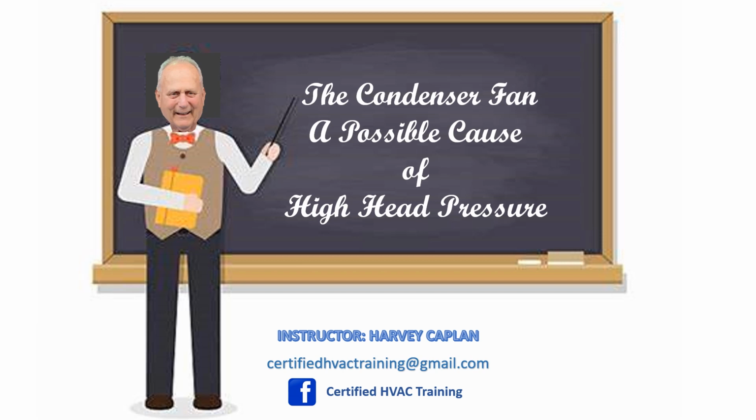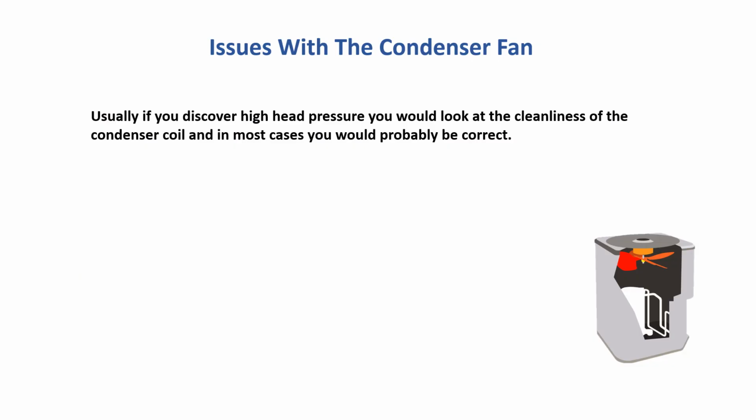In this video, we will be discussing the condenser fan and motor, a possible cause of high head pressure. Let's look at the issues with the condenser fan. Usually, if you discover high head pressure, you would look at the cleanliness of the condenser coil, and in most cases, you would probably be correct. The thing that is sometimes overlooked is the condenser fan.